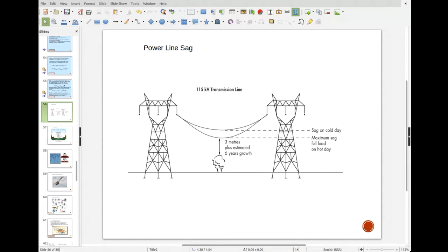And so if these wires get close enough, they act like another resistor attached to it. And so they don't necessarily just short out the circuit and blow the circuit breaker, but they actually just act like more load, like people hooking up more load.